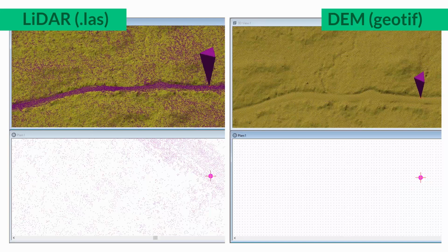Whereas the DEM data is often fine to use interchangeably, but if it was something like an existing road with a shallow ditch, by simplifying that surface down to whatever grid spacing your DEM has, maybe you lose out in being able to actually tell that there's a ditch there.